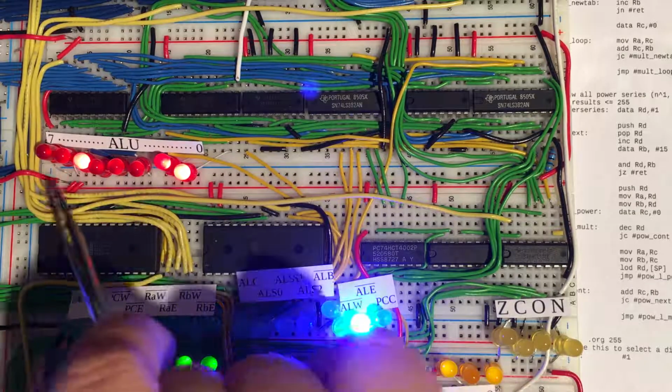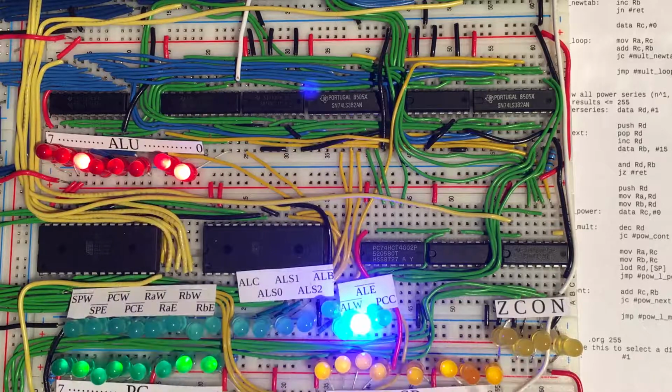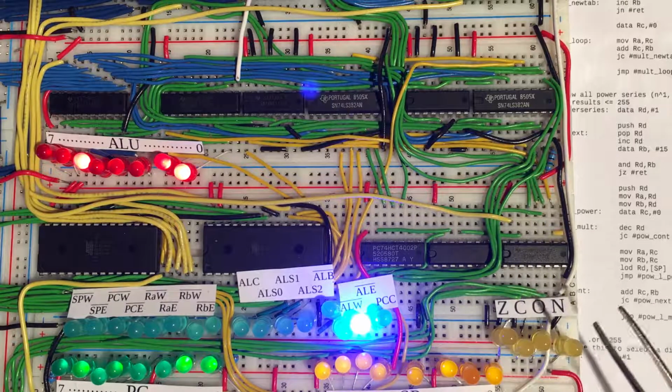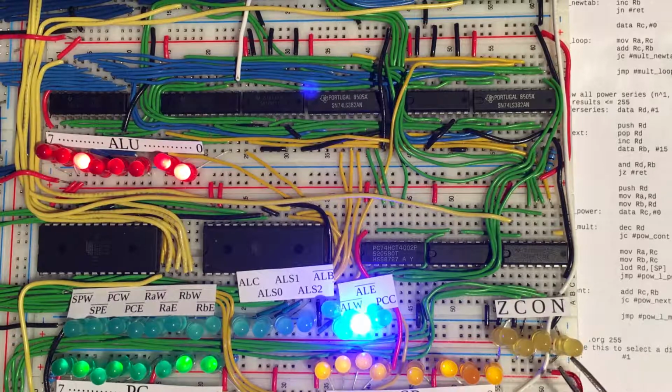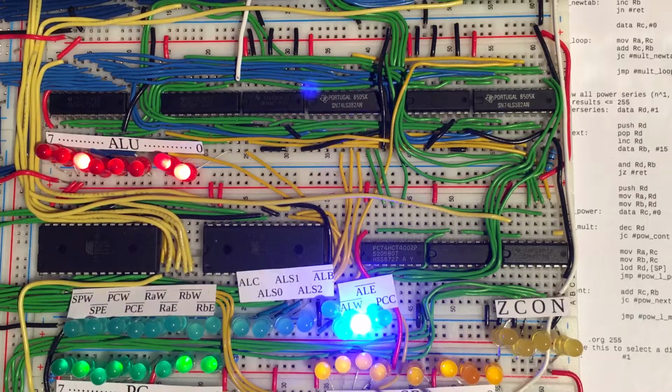And so at any time when we write the result of a calculation into that register, we also set these flags. So that's a 0, a carry, an overflow, and a negative flag. And those are also set by the condition and the state of the calculation at the same time when we write the actual result of the operation.